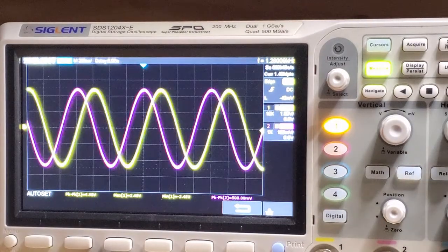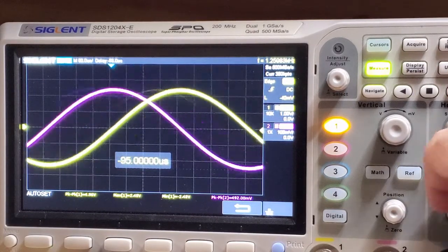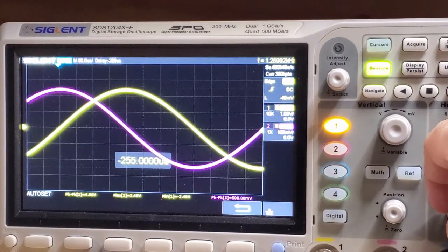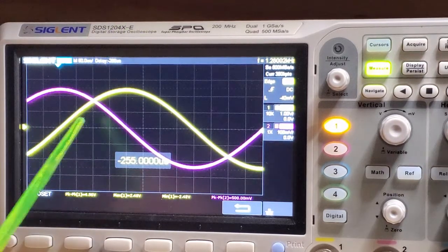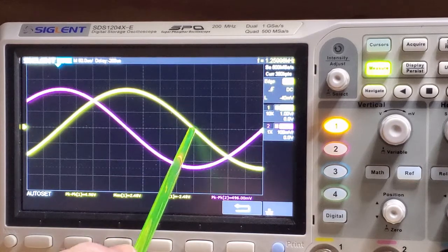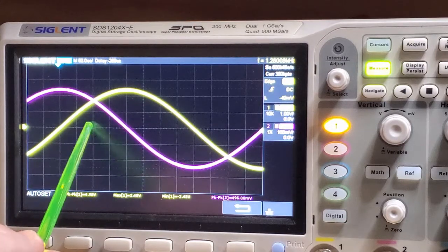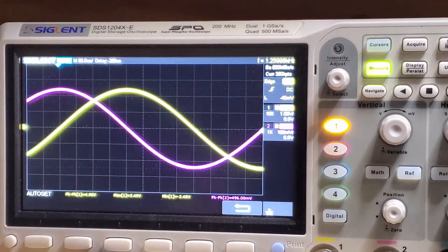Bear with me. And let's do the eyeball check here again. Let's get this centered on a reticle there. So for a half wave, it's 1, 2, 3, 4, 5, 6, 7, 8. And then between this and the other one is 1, 2, 3, 4. So there's our 90 degrees relationship. So now we've generated, from a single input signal, two signals 90 degrees out of phase with one another at the correct frequency without any attenuation.